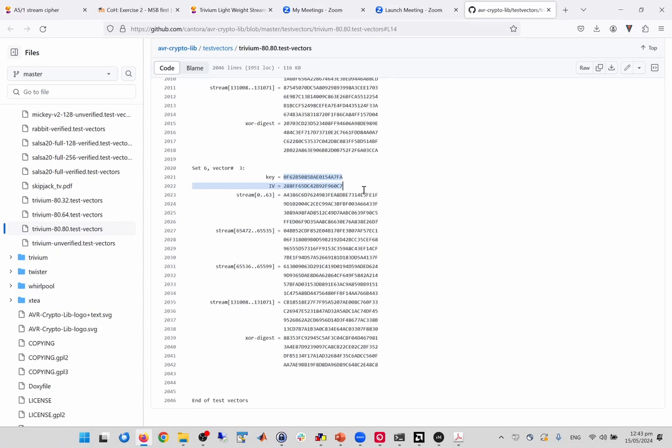You probably know little endian, big endian, and then how the test vectors are generated. I mean the official test vectors, because anybody can build a C model and say, hey, my implementation fits that C model. Of course, but it should actually fit the official test vectors. And then, for the programs which generate or write these test vectors, we should check what the order of the bits is, what the order of the bytes is.